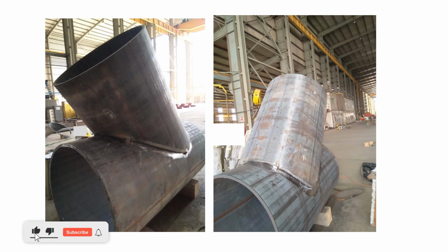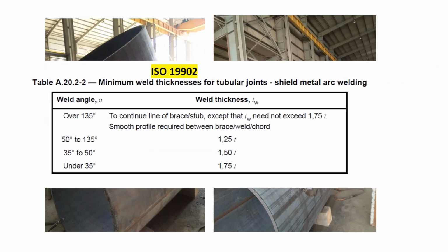Before we start, let's briefly discuss why zone marking is required. Earlier it was discussed that the stress concentration is subject to the localized angle between the intersecting planes. Therefore, various codes and standards specify required weld size and weld profile based on the local dihedral angle. The extract of ISO 19902 shown here denotes weld size as per the given range of dihedral angle.